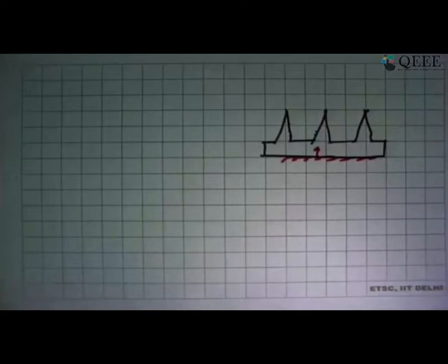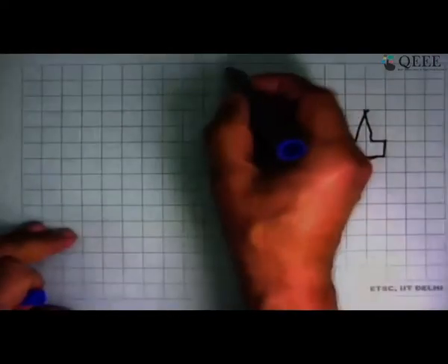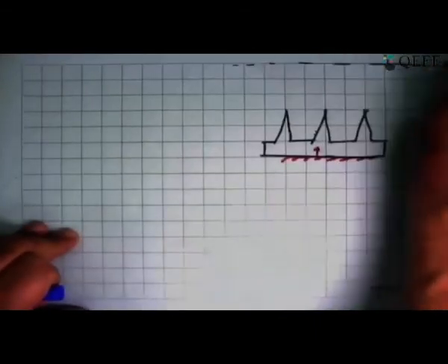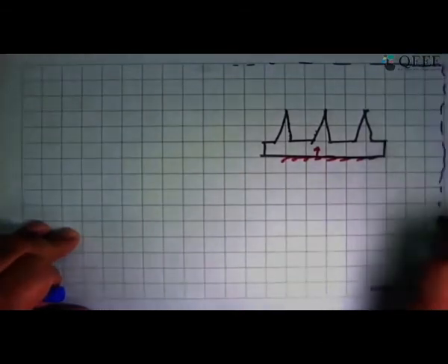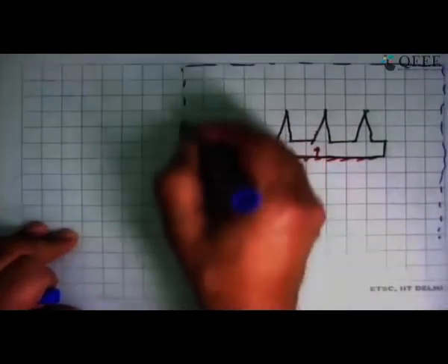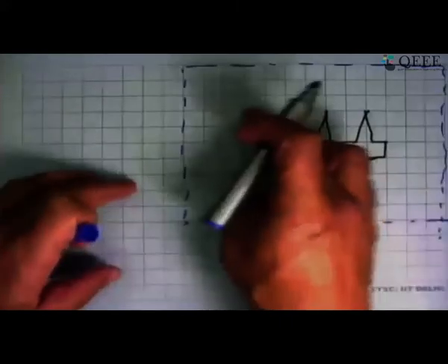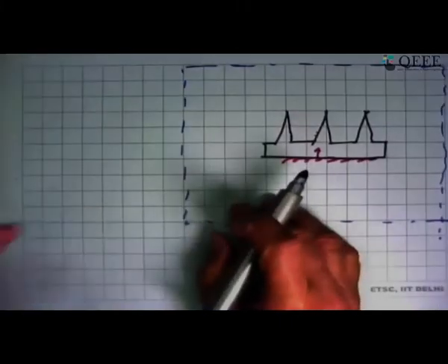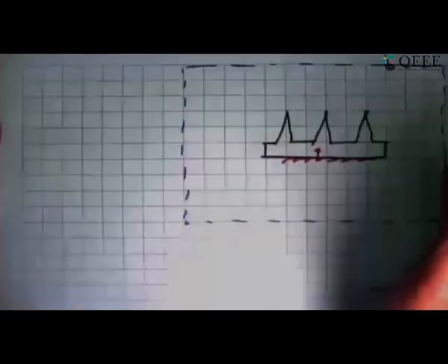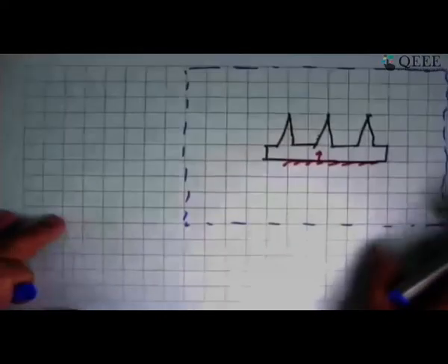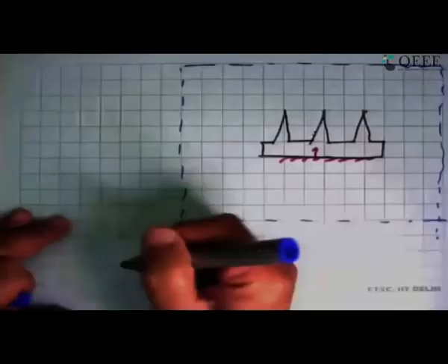And for that we said, look, we need to say, how does heat transfer take place from here to the fluid? So the first thing one does is say, look, what is the size of the airflow or the domain which matters in this problem? If this is, say, about size of an A4 sheet of paper, then this domain may be the size of a room. If I take it slightly bigger than the size of the paper, then your solution will be wrong. And that's the first thing that comes out, when you are trying to solve it.